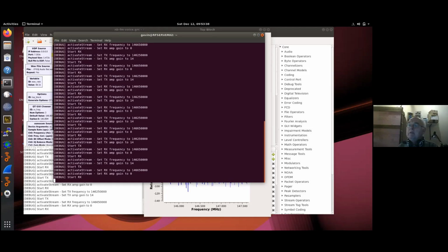Yeah, I use this method with the USB board, and there are various libraries on Linux. I use a board which uses the FT232 chipset from FTDI, and there is actually Python code. There is a library called libftdi, and it also has Python wrappers. So I guess you could try writing maybe a block. I don't know, this depends on how you write your flow graph.